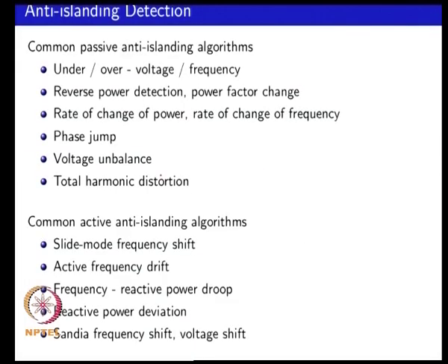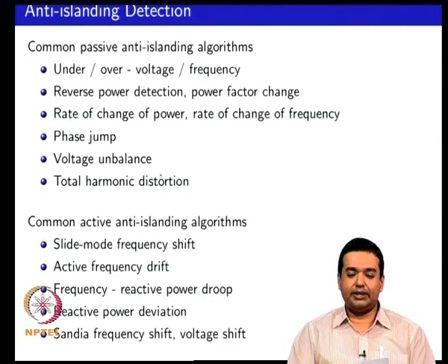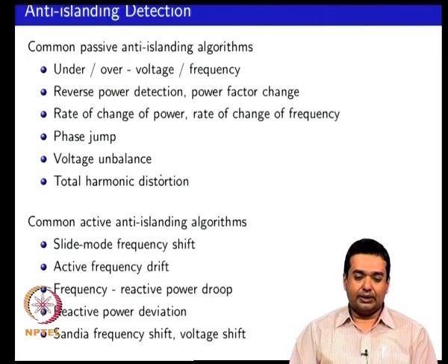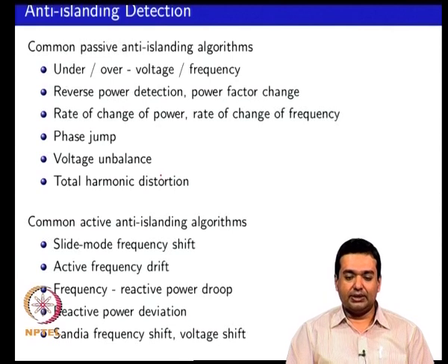So, in literature there are a variety of algorithms that people have looked at, methods that people have looked at for both passive and active anti-islanding. We looked at under and over voltage, under over frequency. We also looked at reverse power flow based detection.